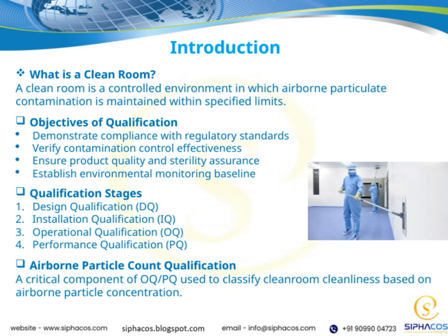Now, the qualification process itself involves several stages. Design qualification, or DQ, ensures the design of the clean room meets all specifications. Installation qualification, IQ, confirms that the environment and equipment are installed correctly. Operational qualification, OQ, tests that the system operates as intended under normal conditions. And performance qualification, PQ, verifies that the clean room performs consistently during actual operation.